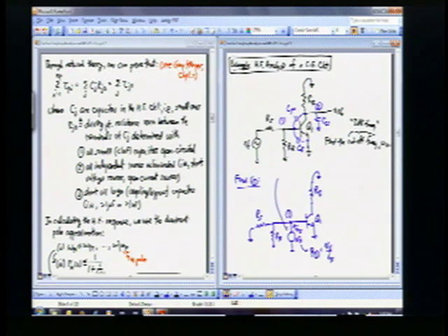And you notice that voltage source is taking up the position where C-pi used to be. So let me just write that. Takes up the C-pi position. The additional thing that happened in going from that circuit to that circuit is that C-pi, C-mu, and CCS all got open circuited, because they are the small, less than 1 nanofarad capacitors. Let me write that down too. Less than 1 nanofarad caps.